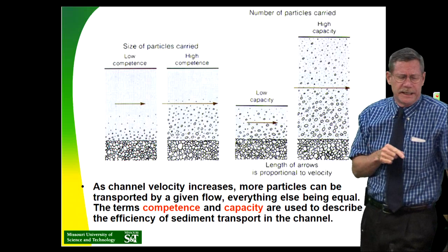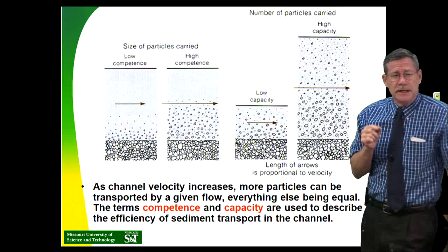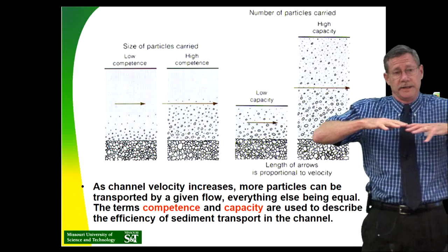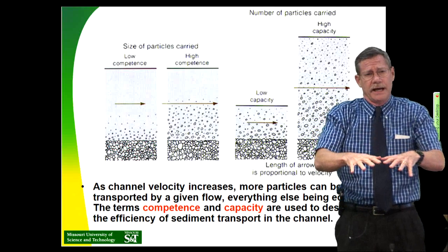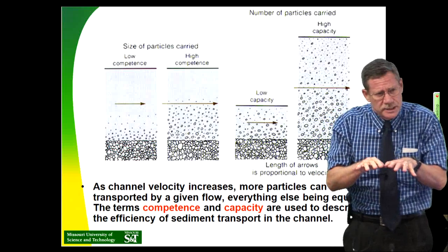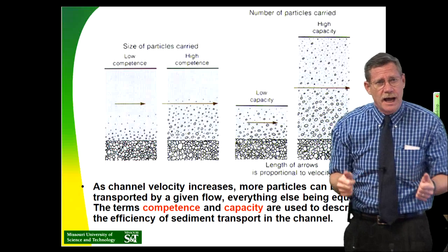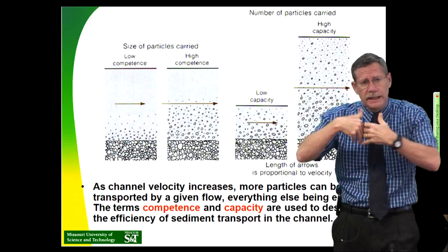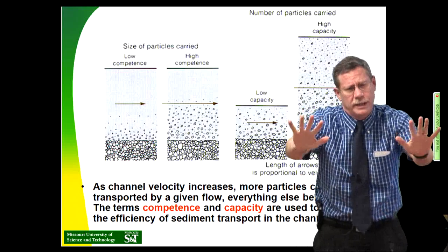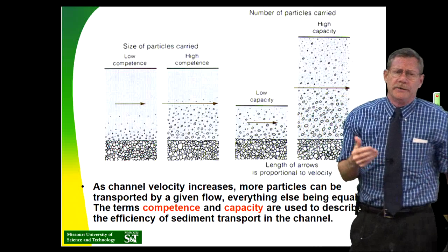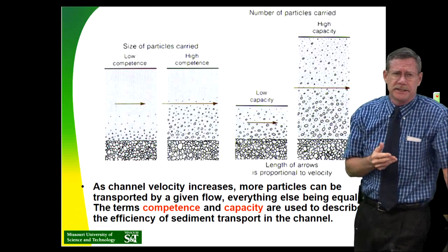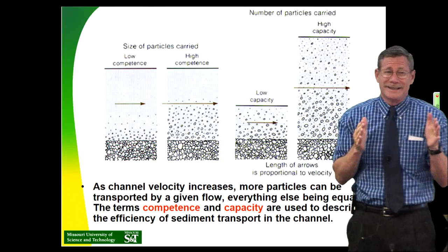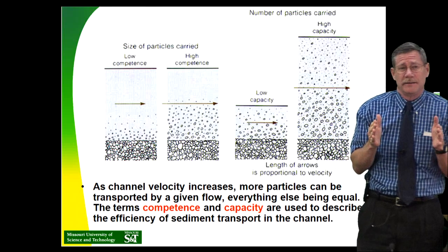What's going to happen is you're going to get a whole bunch of water piling up and dumping sediment at the upper end, and then as it flows through this nice smooth box, the competence and capacity is going to go way up, and it's just going to clean it out, and you're going to dig a huge hole at the end of it. So in that kind of situation, if we use a universal cross-section, it's not going to be very hydraulically efficient.